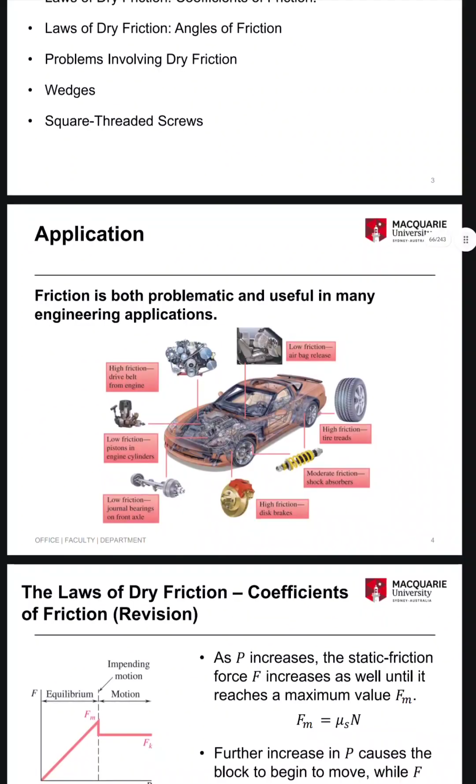Application: friction is both problematic and useful in many engineering applications. High friction: drive belt from engine. Low friction: pistons in engine cylinders, journal bearings on front axle. High friction: disc brakes. Moderate friction: shock absorber. High friction: tire treads. Low friction: airbag release.